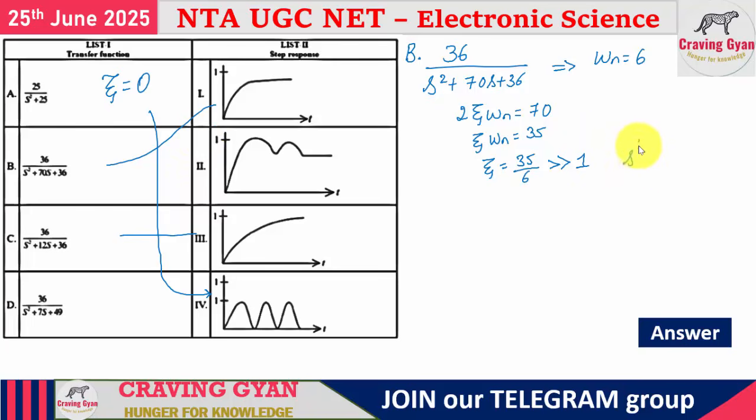So zeta very much greater than 1 means what? A very, very slow response, or rugged response, you are going to get. Now look at the things. Zeta value greater than 1, okay, but very much greater than 1 means chances are that your system may lose the stability. Your system is going to lose the stability.